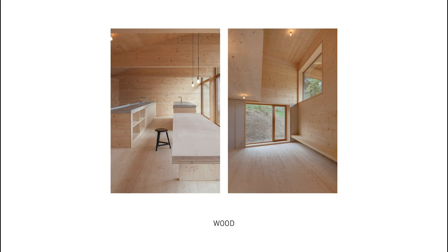Although wood is not a popular material considering massive construction, it can be used, as shown in the following example. Aside from the reinforced concrete foundations and the walls in contact with the ground, it is a purely wooden structure. Thanks to the high degree of prefabrication, construction lasted just 16 weeks. The exterior walls employ glue-laminated timber. The cantilever is made possible by story-high crosswall elements.